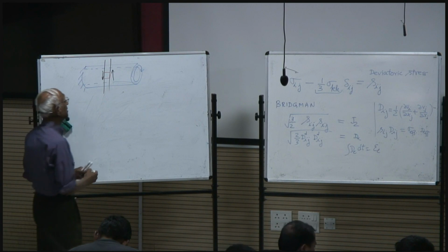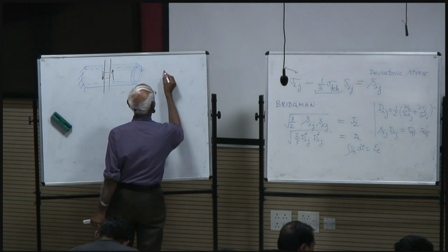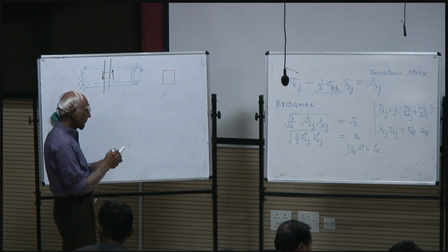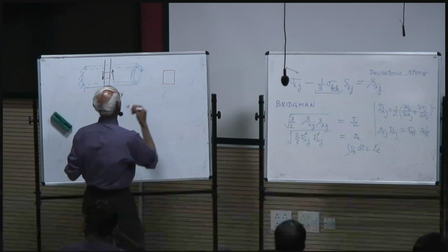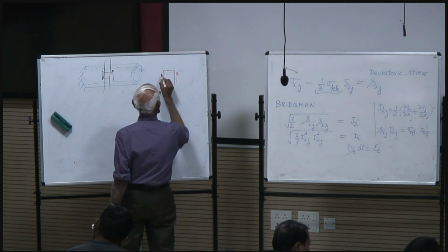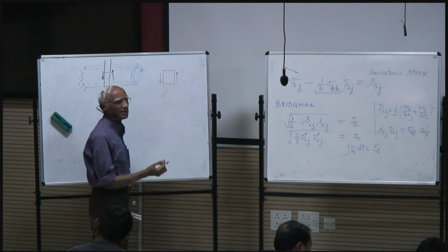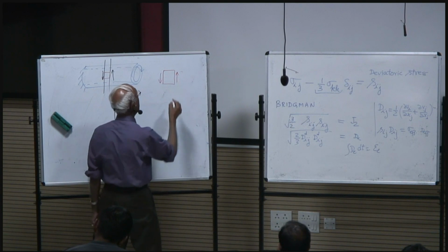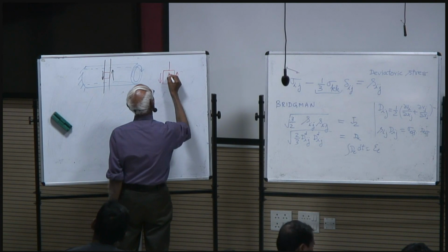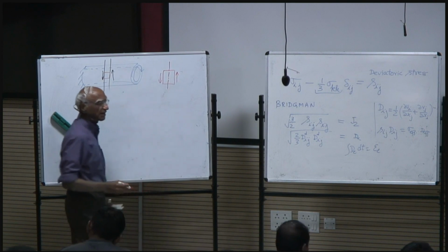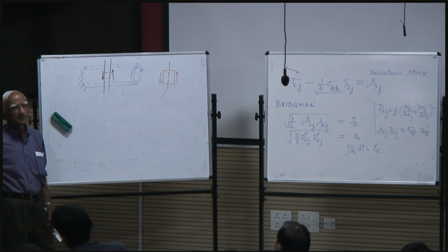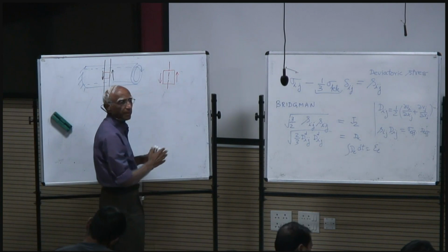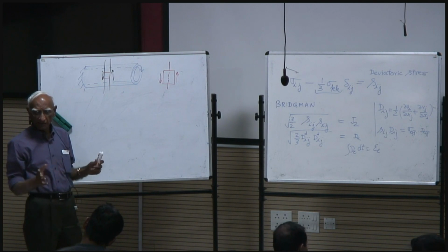And now I should draw the free body diagram of that small piece. That small piece is going this way and that, and if you say it's a shear stress, we must have shear stress on the top and the bottom surface. It's anti-symmetric about this axis. Like this thing is going up and that one is coming. So it's anti-symmetric or skew.